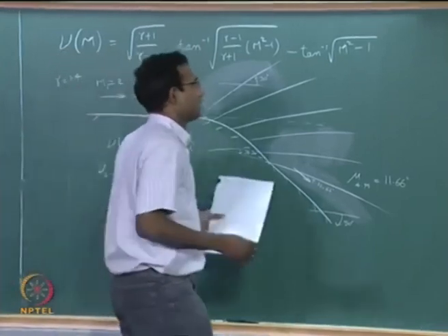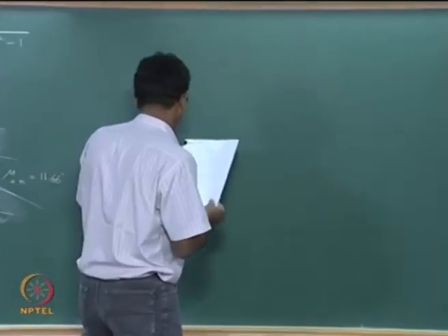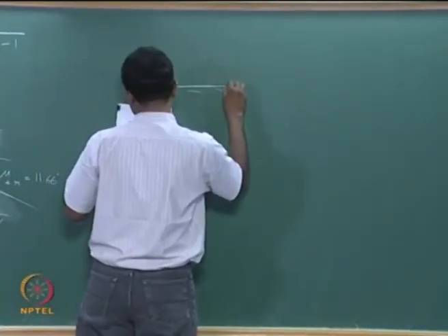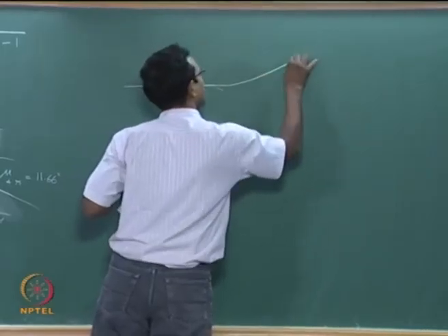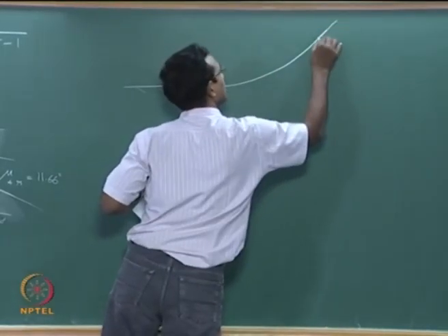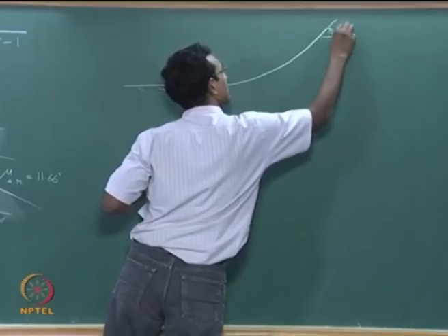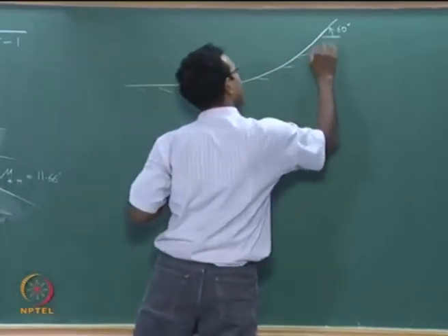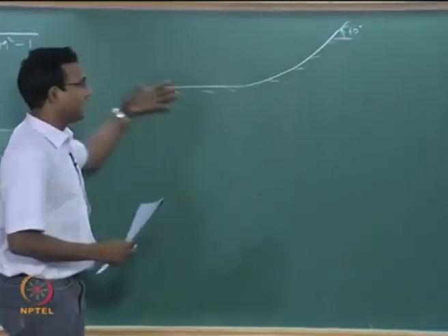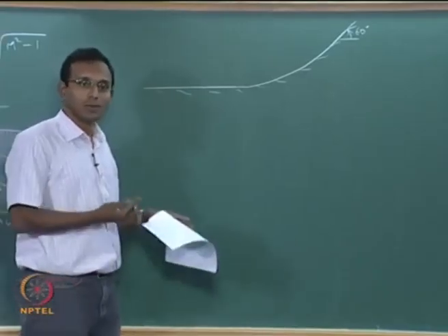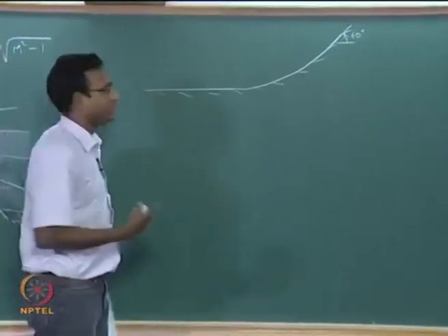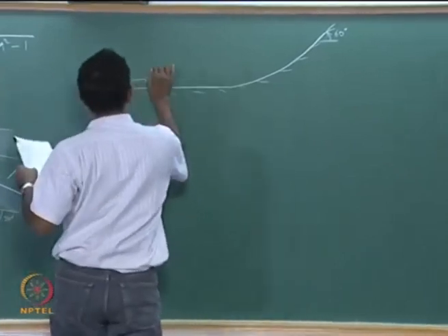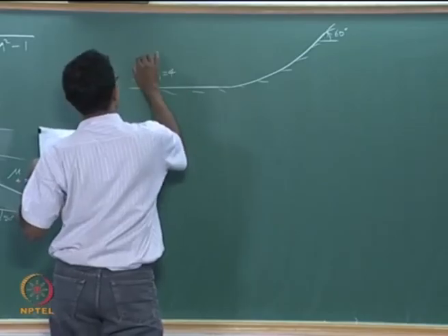Okay. We will keep this, just go for a smooth compression case where I am going to have a wall and it is going to turn to a 60 degree angle. And it is turning into the flow. What does that mean? It is going to block the flow, it is going to decrease the Mach number, so it is a compression wave sitting there. Okay. And I am going to say the incoming Mach number M1 equal to 4, gamma equal to 1.4.